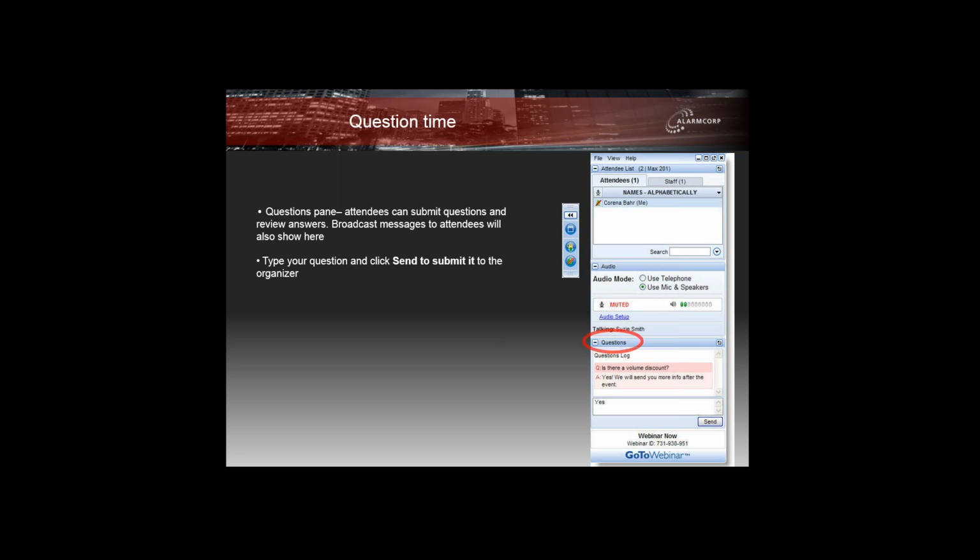It really does reduce the possibility of this device false alarming under certain conditions. The only conditions that you would need to be at least semi-wary of would be if you've mounted seismics on a large concrete structure, and there are other machineries, devices, or equipment located above or below the building that generate a lot of noise and frequency. It might be a big power plant, or all sorts of different types of machinery connected directly to the concrete structure that the seismics are mounted on.